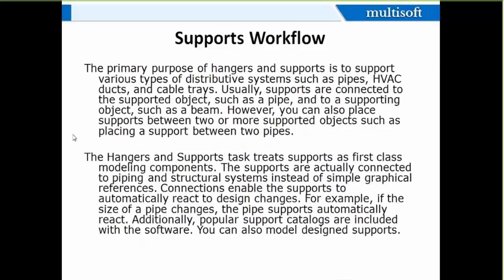Next, supports workflow. As I told, we have different types of supports. One is the logical support and another is the design support. As I told, from the piping point of view, supports also, you will place the support assembly. So you need not model your supports part by part. Automatically you can model the supports as an assembly. If you still want to place part by part, that is also possible. But if you place by the part method, it is a time-taking activity. If you place a support assembly directly, 100 times you can copy paste that particular support assembly. By part means it's very difficult.